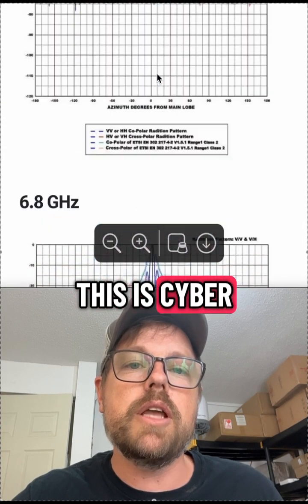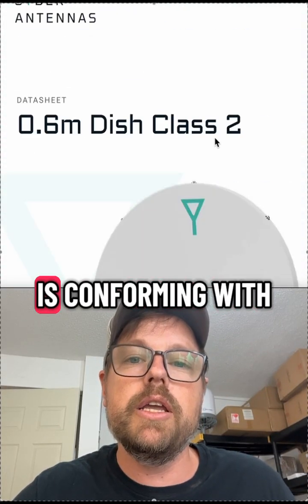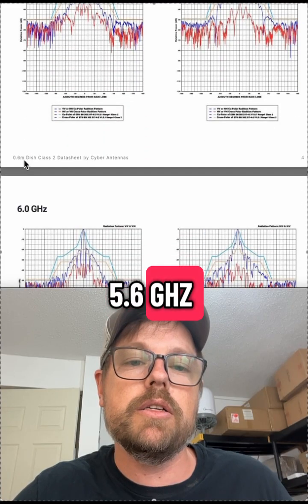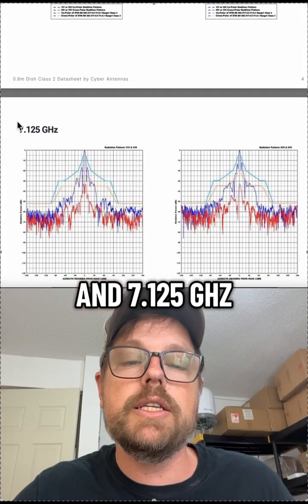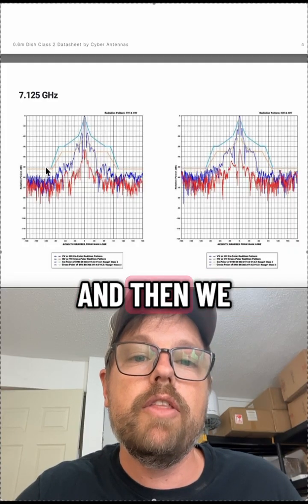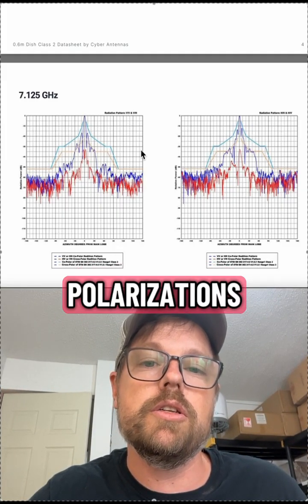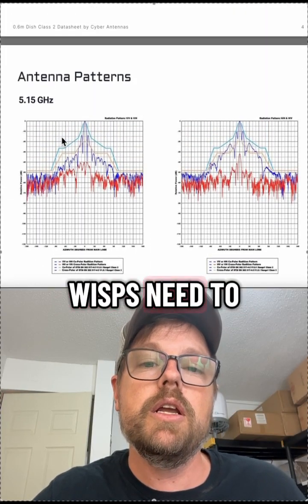This is Cyber Antennas' class 2 dish. The class 2 is conforming with ETSI standards, and we have 5.1 gigahertz, 5.6 gigahertz, 6.0 gigahertz, 6.8 gigahertz, and 7.125 gigahertz. So that's 5 different frequency points, and then we show the ETSI mask on each one of them. We have vertical and horizontal polarizations. So you get an incredible amount of detail, and this is the detail that WISPs need to understand how to use our antennas.